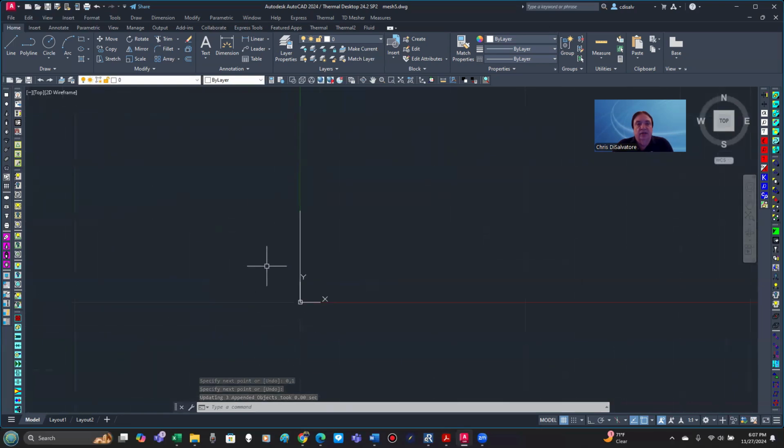So as you can see, that feature is generated. Since I was in the line command, I can go ahead and enter again. Go back to the line command, and I'm going to generate another line to the right of this, twice as long. So the start point of that line is going to be 1 in the X and 0 in the Y.